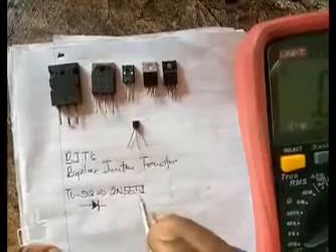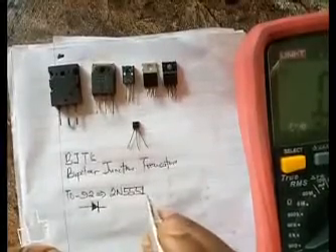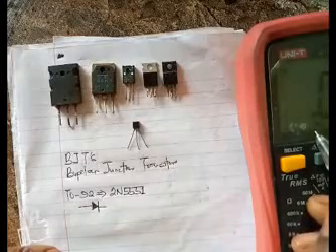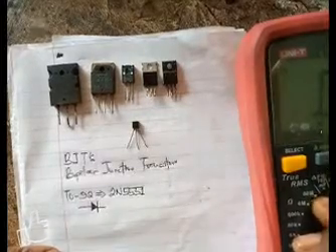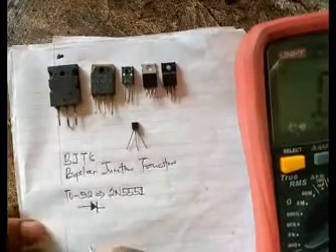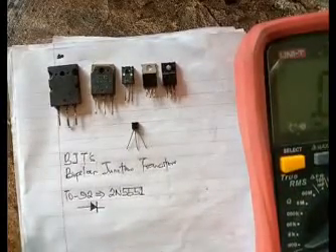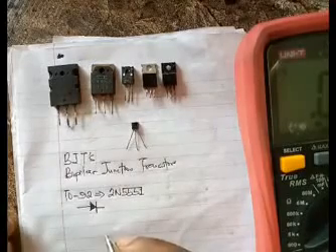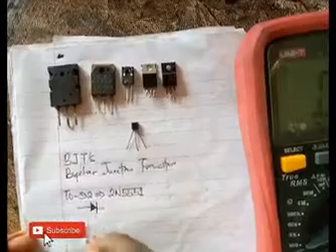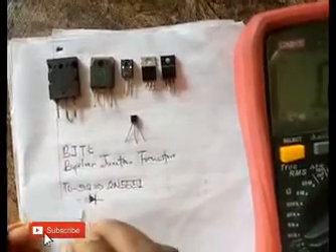So whenever you want to test a BJT transistor, you make use of your diode measurement. Okay, and now it will make sense if I put it this way. Every transistor looks like two diodes arranged back to back. Now let me tell you what I mean. You see this particular diode.